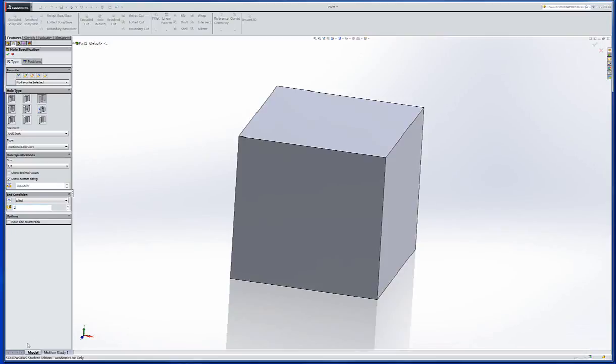Let's just go halfway through. We'll go 2 inches. And then you have some other options here, near side countersink, if you want to put a countersink on the hole as it goes through. Sometimes that's used as a quote-unquote lead-in, and you can change the angle here, 90 degrees. A lot of times that'll be 82 degrees for a machine screw.